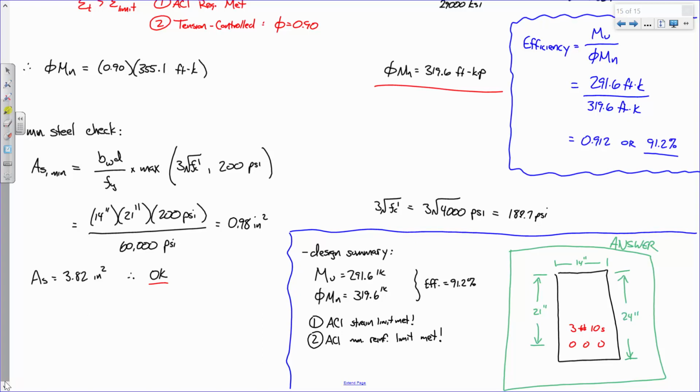What could you do to make that beam stronger? Increase the area of steel. Okay, so number 1, the steel. You could up the steel or change the steel, and that's going to change the capacity. What else would change the capacity? Increasing surface area. So what do you mean by that? Like the width or the depth. Okay, so those are 2. There's B and D. There's 2 other parameters that we can change.